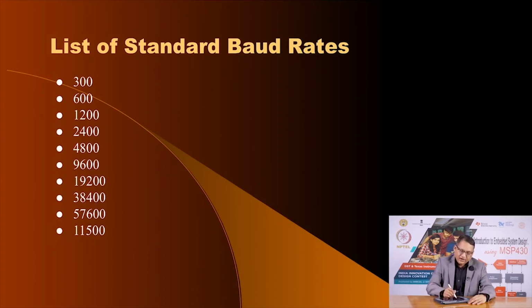Now, the meaning of standard baud rates is that if you have an existing device, let us say a standard laptop or desktop, which would offer certain serial communication protocols, it would offer communication rates from one of these numbers. Of course, if both the devices that want to communicate using the UART protocol are your devices, you can choose arbitrary rates of communication.